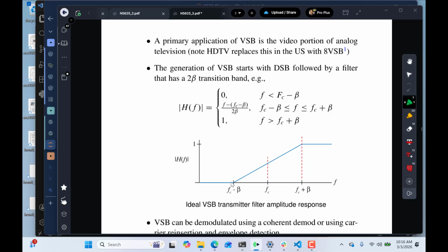So this is sort of what the effective response is. If this is the carrier you're going to pass with this gain slope on it, the upper sideband, and then you have a sort of an anti-symmetric negative, and the way I like to visualize it is when this lower half folds around in the demodulation operation, this will fill in that attenuation that you see there.